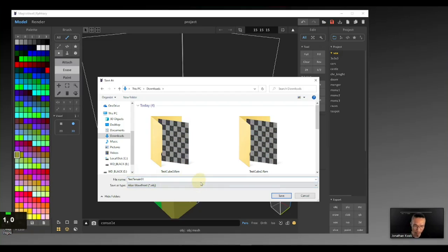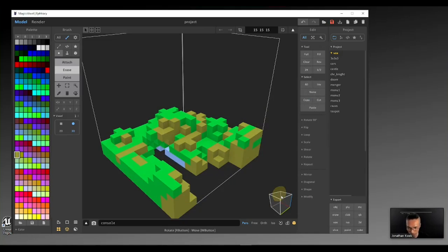So we're going to use an OBJ format. Now, we used an FBX format just now, and we're using an OBJ format this time. A lot of y'all will really like to use OBJ format. It's also a very common format to use, and it works perfectly for things like static meshes. So mesh data and texture data, UV channels, OBJ is perfectly fine to use. The only thing that OBJ doesn't support in our workflow is bones and animation. So this is something for you all to consider. If you're just creating some basic static assets, OBJ will work just fine.